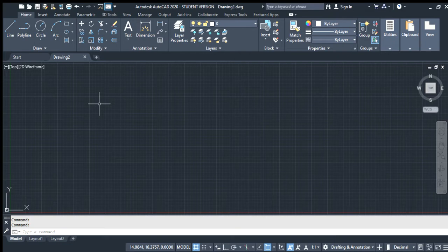Before we start drawing anything, we're going to go down here and make sure we have ortho mode and grid mode on. We'll make sure we have ortho mode turned on, and we'll make sure we have snap mode turned on. The snap mode is going to have, I'm not sure if you can see this pop up, but make sure you have the endpoints, the center, the quadrant, and the intersection selected, which I do. I have got all those selected, so I'm good here.